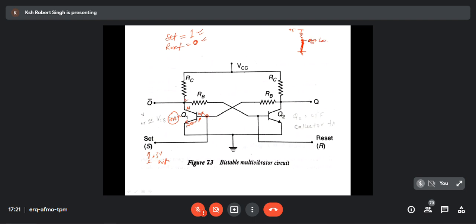So the voltage over here will be low, and this voltage is connected over here, that means to Q2. Here also the direction says this should be positive, this should be negative. So this is nothing but an NPN transistor. Why do I say NPN transistor? Because this arrow indicates the current direction. This is an emitter to base connection. Emitter to base will always be forward bias, and the arrow indicates the direction of the current. That means current goes from positive to negative. So in order to make forward bias, this should be connected to positive, and this should be negative.